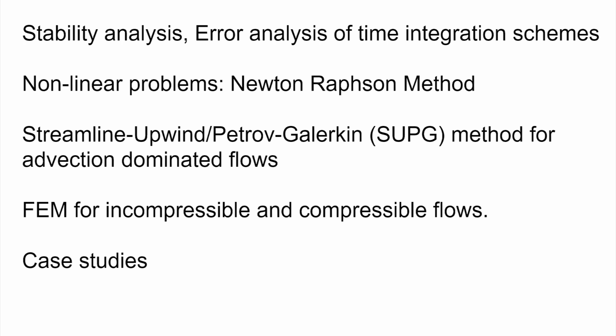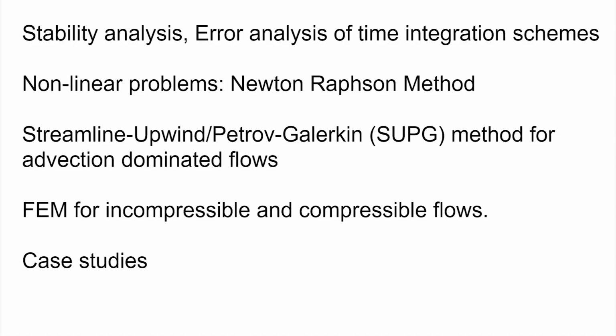Having done that, now we will move our attention to nonlinear problems. So, how do you solve a nonlinear problem? Usually the method is you linearize it locally, and for that we will use the standard Newton-Raphson method. It is a second order method, and then how do we implement it in the finite element method? I will talk a little bit about that.